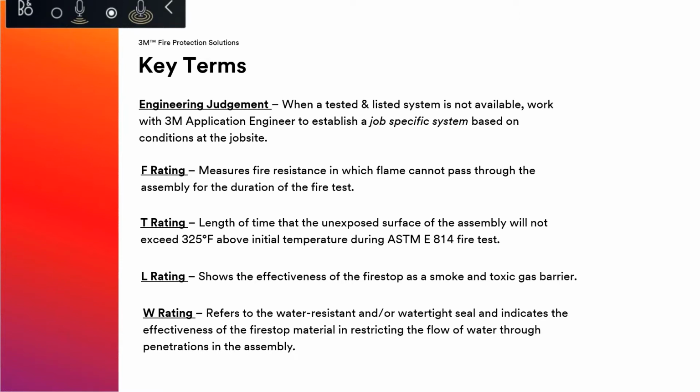If there's weather storms that come through before the exterior or the roof is on the building, they don't want weather to hit the firestop products and wash them out, or they don't want the rain to get through the firestop materials down into a finished area of the building during construction. Or maybe, like I said, the owner wants it because the only separation from one high-end unit to another high-end unit to stop flooding is the firestop materials.